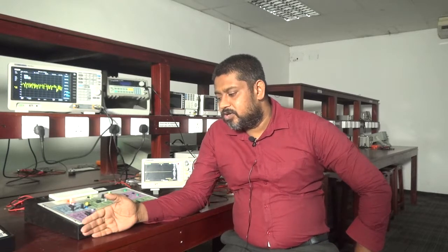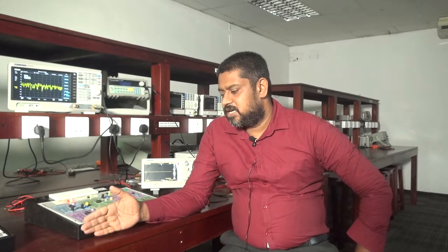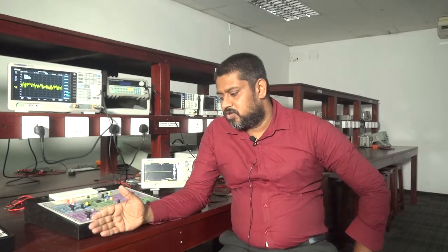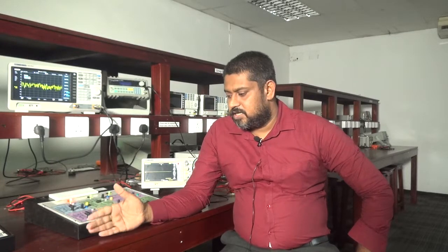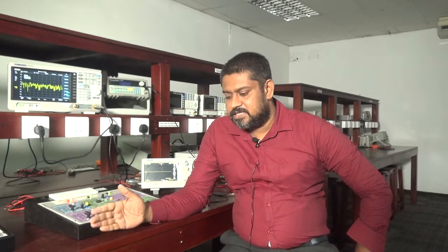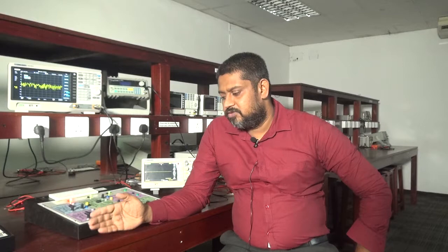You already know that in conventional AM modulation, we will have the carrier signal with the modulated signal, but that carrier signal doesn't have any information. If we send the total spectrum, we need more power to transmit the signal, because the carrier has very large power in it. So it is a waste of power.